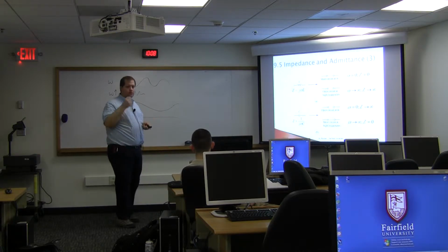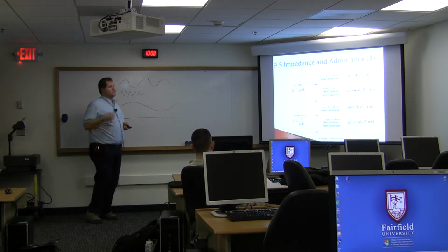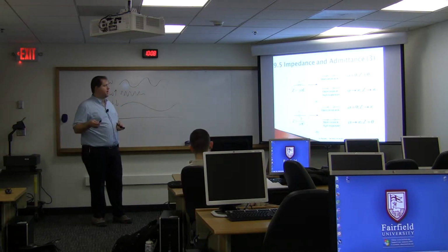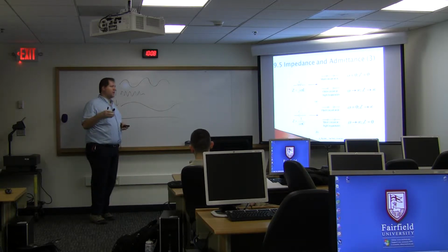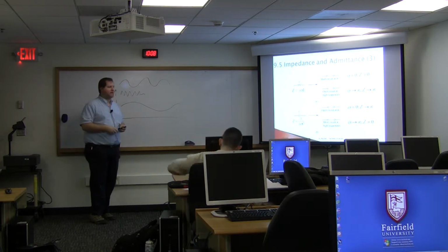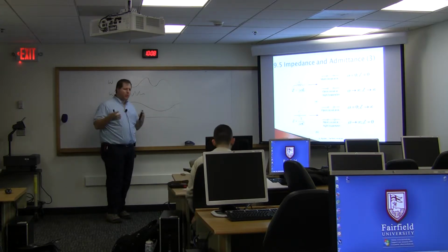Right? Is there like a limit where... Typically we'll see this when we do the filtering part. They'll often define the 3 dB point. So they'll define the point where basically the power cuts in half. We'll talk about the decibel scale and what exactly that means in later chapters. But that is sort of where people define it, and they'll call it the corner frequency.